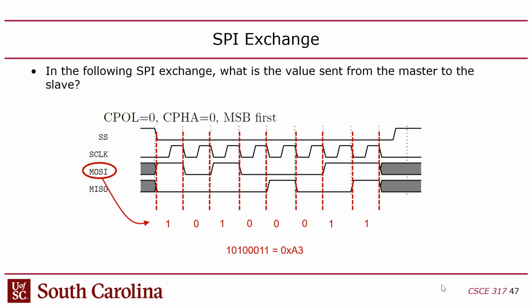So remember, in the last timing diagram, the dotted lines were the read points, but now you have to read between the dotted lines when you're reading these bits. So MOSI would be 1010. Notice that my red dotted lines and the dotted lines that were originally in the waveform are now aligned with one another, and so the read points are in the middle. You guys with me?